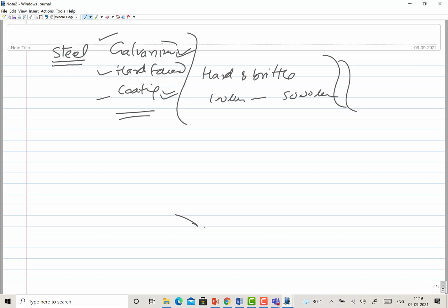Hard faced layers are thicker ones. These can be very hard and brittle, or can also produce low melting point constituents. So the thickness can vary, the mechanical properties can be significantly different. These can also get dissolved during the joining process.